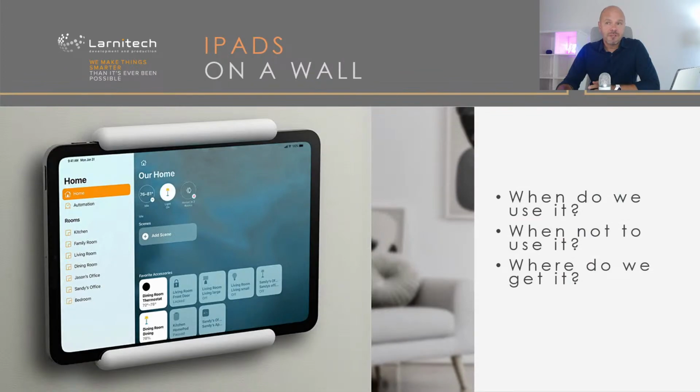And on the wall you can also use iPads. And iPads we use when client says I am the fan of Apple and I like how iPad looks like, and not use iPads if client says please do not use Wi-Fi. So if client is okay with Wi-Fi, then iPad. If you need a wired connection to the network, maybe better use our previous panels. There are solutions for wired connection to network for iPad, but keep in mind two things about iPads.